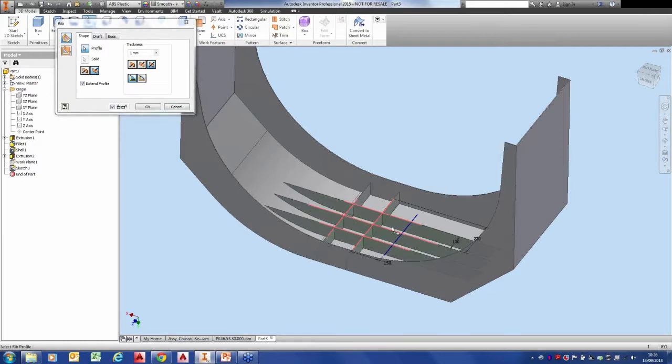And you can see immediately it just extrudes the lines to the extents. Because I put the work plane just below the surface, so it's below this edge here where the cursor's displaying at the moment, it's going to the next edges available.